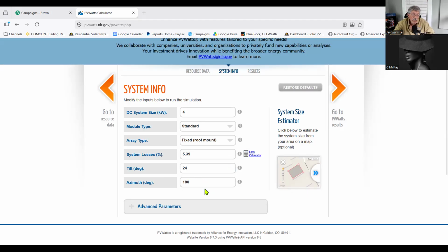And then you're going to need to figure out its azimuth, or what is the orientation of the building. Once again, you can use a design tool that utilizes Google Earth, which will get you that, or you can measure it on the site. 180 is south, solar south. 0 is solar north. 90 is solar east, and 270 is solar west. So that's how you would figure that. Let's say 180, that'd be perfectly facing south. Let's say it's not quite facing south perfectly, it's 167.